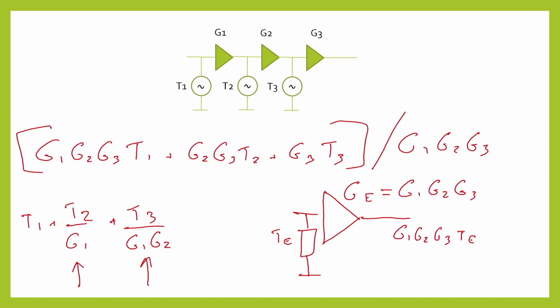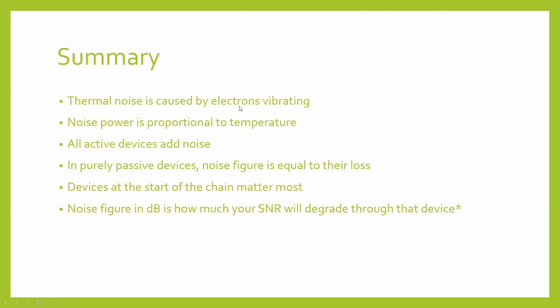I will stress that there are formulas for directly working in terms of noise figure or noise factor and cascading them between multiple devices, but you end up with a lot of minus ones in the formula that are easy to get in the wrong place or forget, so I tend to work in temperature as I find this expression much more straightforward. Right, that's quite a lot of theory for one day, so I'll just summarise and then we'll move on to practical stuff next time.